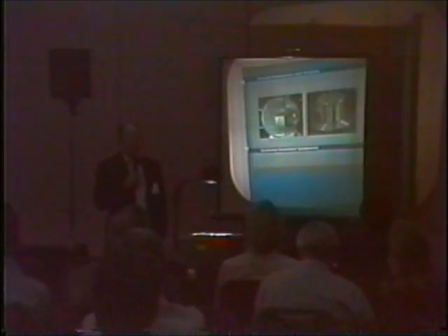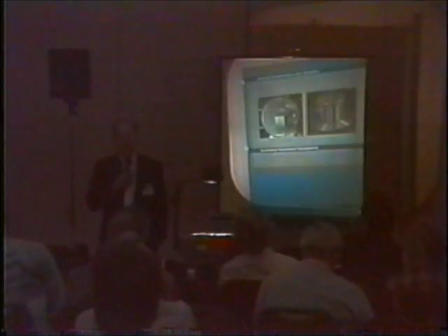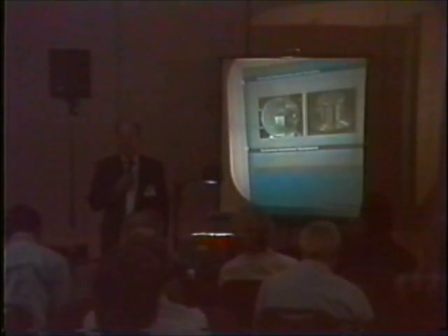The reason for that is that a Marx generator has a lot of plasma display going on around it. You have the ionization of the air and other things around you in such a way that it will interfere with a lot of things. It'll short out the Marx generator, and it creates all kinds of interesting electrical problems. So in order to contain and control it, you put it inside a tank and you fill the tank with oil.